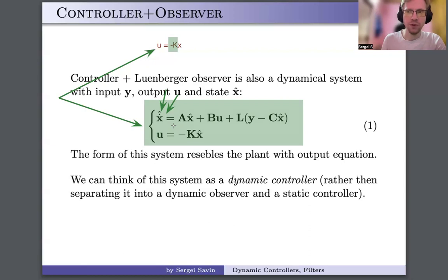So the control scheme would have to be operable at the frequency of your updates. So like variable step integration is not going to work, right? So that is, from programming perspective, a big difference between those two controllers. Dynamic controllers would always have this kind of problem, right? Static controllers never do.